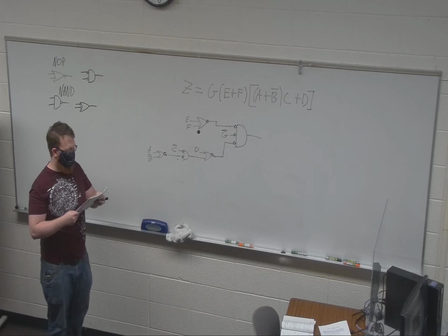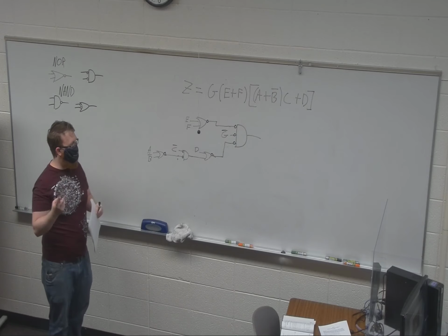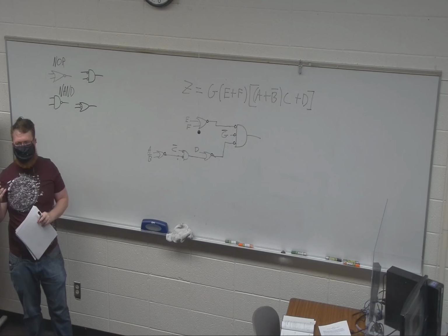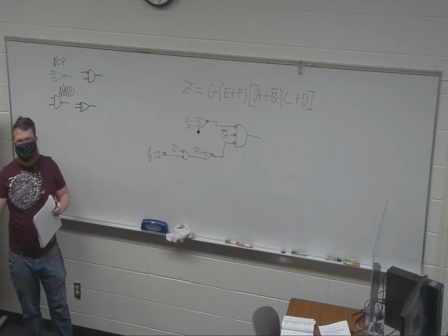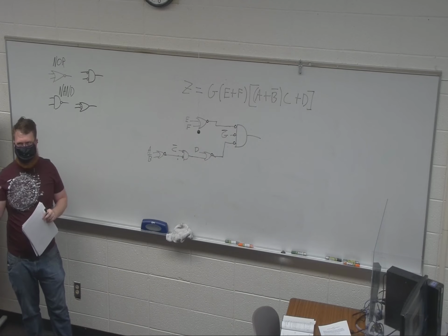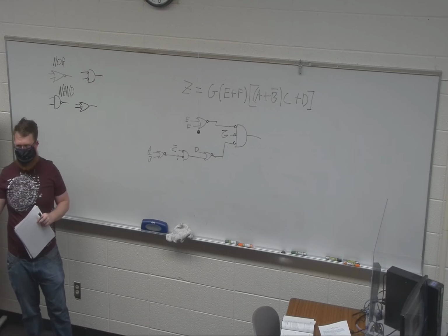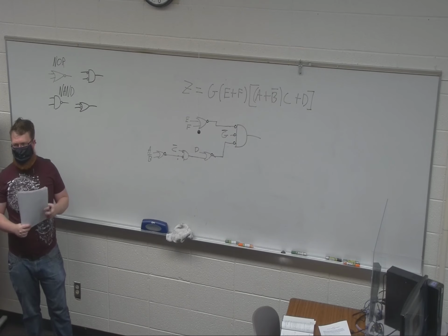And if you want, all that you have to do is to flip the gate type. So we got all NORs. If you want all NANDs, I'm a little confused. I can't remember which one's which. One of them you're circling the ones on a K-map to write the equation, and the other one you're just circling the zeros, and you'll generate the two different types of logic.